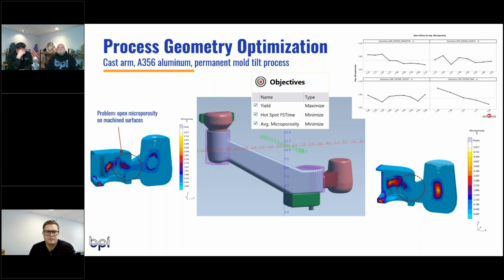And so in this sense, the software allows you a much more accurate capture of that interaction. And so you're optimizing your feeders not only using the size of the part and the surface area, but also accounting for the alloy properties and the sand mold or the molding media material properties. So, that's a great question. We use a result called feeding modulus. We look at the value of the major feeding modulus in the part, and then we backward calculate a starting point for some of these feeders, and then move right into the optimization phase.